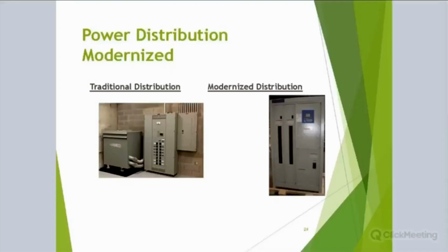It takes added install costs because the contractors must interconnect those two, set them, feed each one. To where on the right side is a power distribution unit, which is the same equipment. It's one single box with the transformer in it, with the panel board built into it.